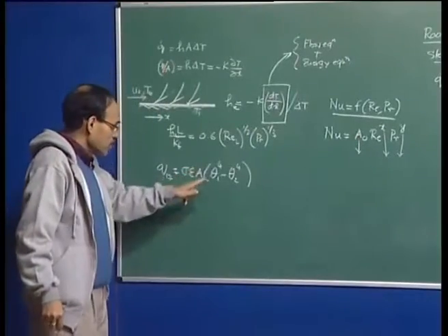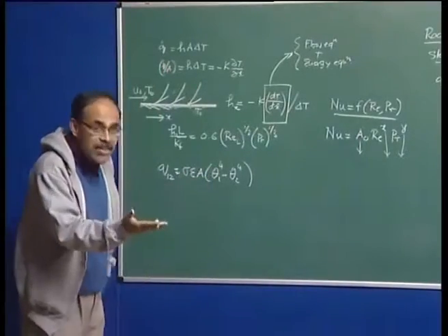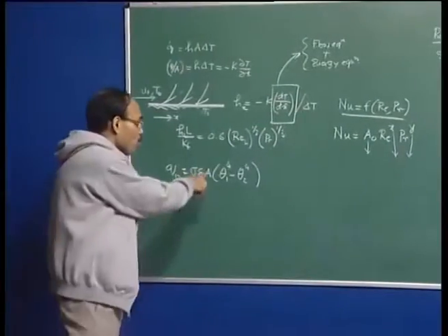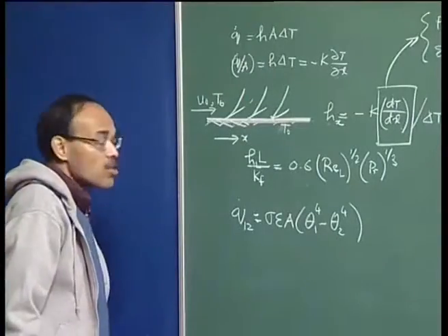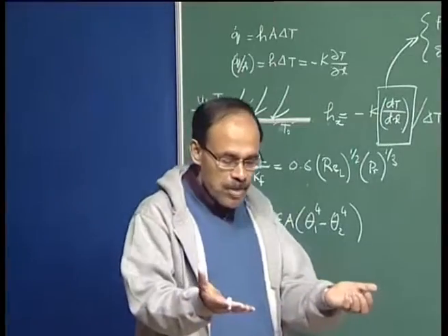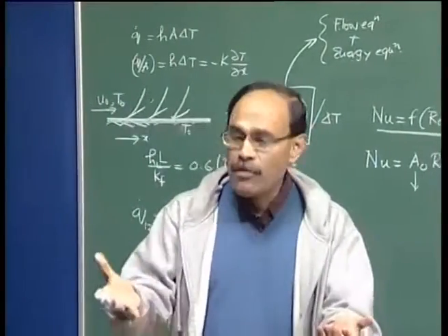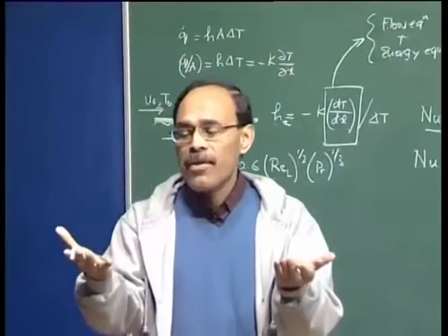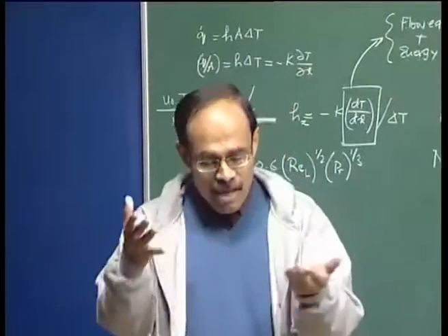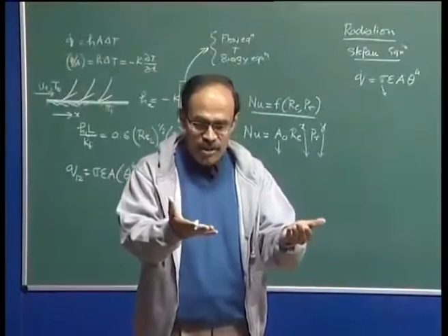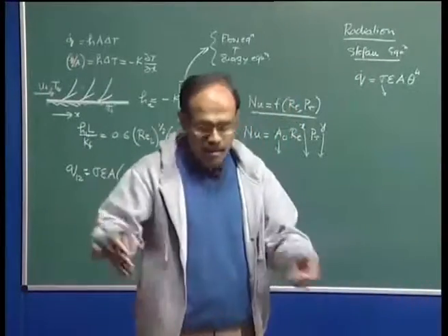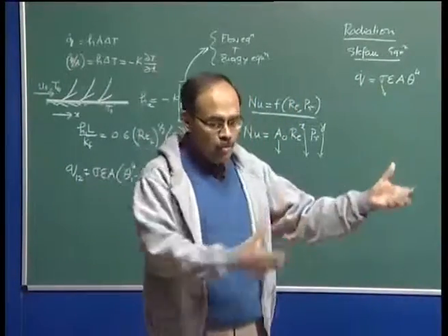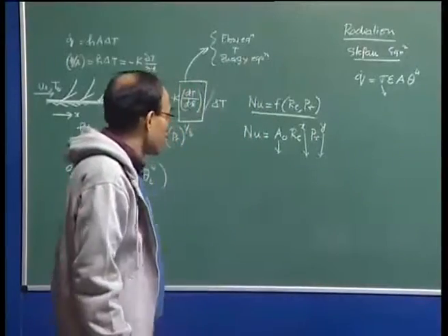Now, this essentially tells us that as the temperature increases, the contribution of radiation is going to be extremely large. Imagine, for example, a solidified slab, which is at a very high temperature, maybe surface temperature is about 1000 degrees centigrade, and then you just keep it outside, and on a normal day you have a breeze blowing over the slab.